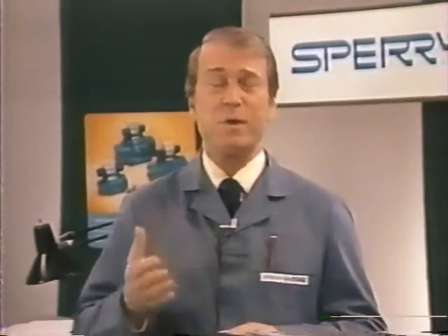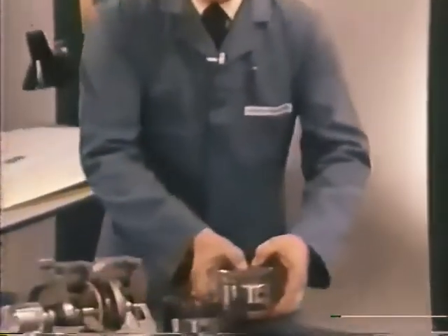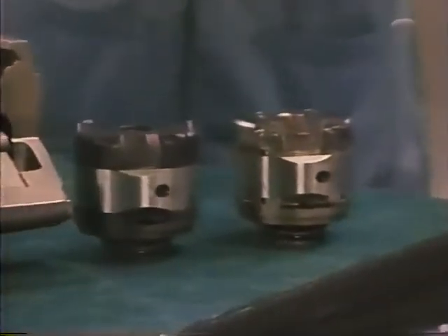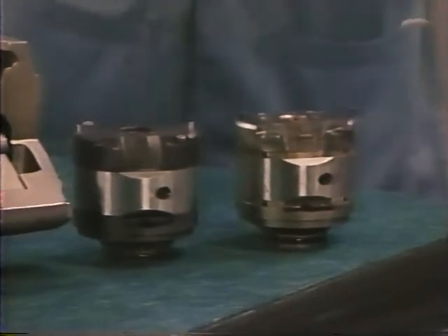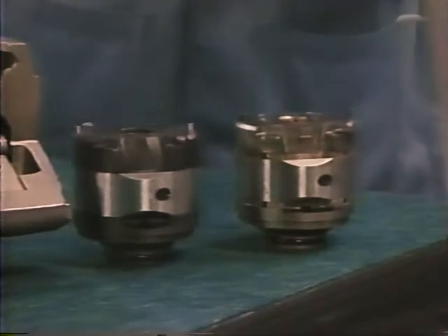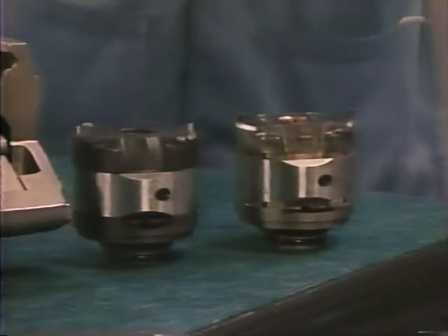The intravane is used successfully in high-pressure machinery and in press circuits as well as mobile vehicles. To make it more compatible with the temperature extremes in which mobile units must operate, bronze-faced steel flex plates have been added to the cartridge assembly. They're much like, and serve the same purpose as, those mentioned previously in our discussion on gear pumps. Although interchangeable with the original intravane cartridge, they're not required and unlikely to be used for machine tool application at the present time.